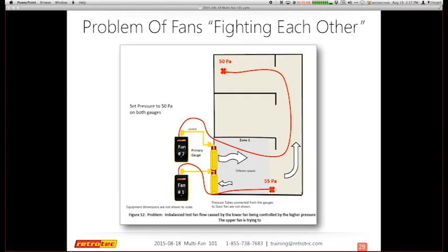So here's where the 2-fan scenario, or the multi-fan dilemma, comes into play. When I have 2 fans working in the same zone or trying to work on the same area, one can slightly over-dominate the other, and next thing you know, one fan is moving slower and slower, or has basically stopped, or is actually working in reverse because the air just gets pulled back through it, right?